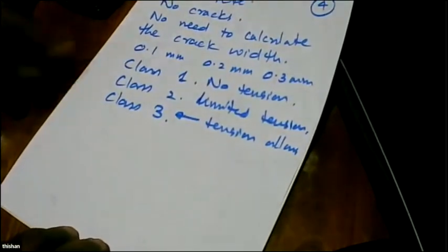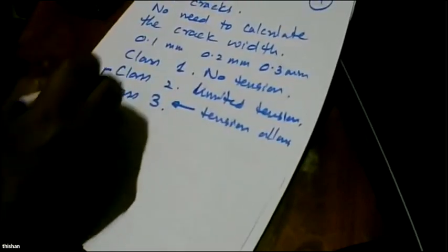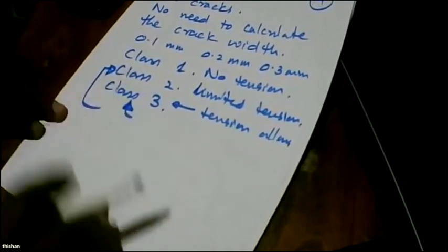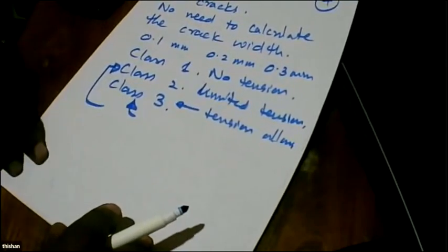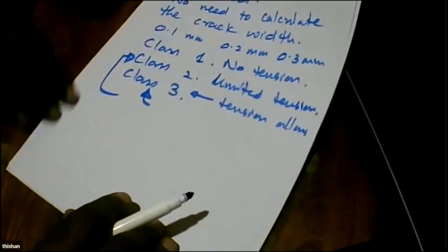So you will find most of the structures that we see have been designed as class 2 structures. But some engineers like class 3 structures as well. So you can go for tension. And if you go for tension, you must do a crack width calculation and find the crack width and see up to which value you have to limit it. So all three are okay